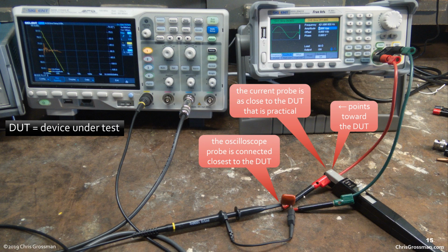And then the leads from the function generator are connected after that. And then I have the current probe as close to this as I can get. Now, from here to where about the tip of the scope probe is over to the current probe, it's capacitance from this over to this area that can cause problems.